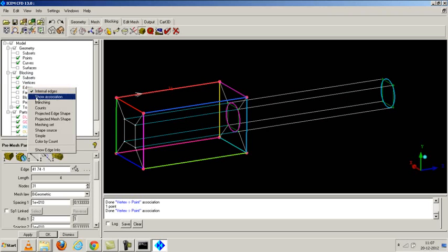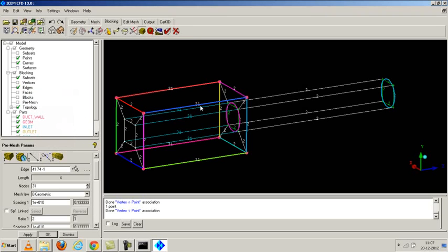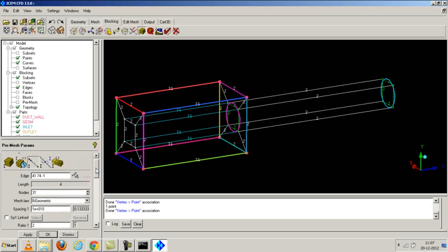And if I display the number of cell counts on each and every edge, the edge opposite to the particular edge which I selected also gets the same number of nodes copied. This is the rule or beauty of structured multi-block, because it has to follow the same pattern of mesh elements.